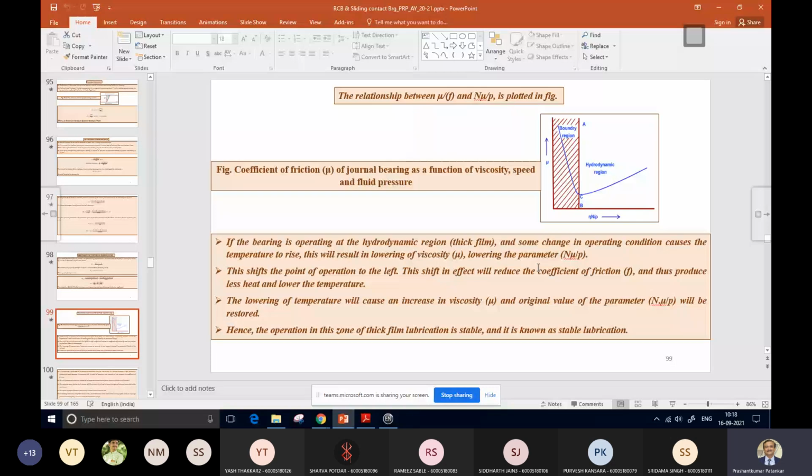After some time, when the temperature of the oil increases, that higher temperature oil is recirculated to the oil sump, wherein a provision is made to cool it, and it is again recirculated back to the bearing. That kind of thing is done, but it is costlier. So as far as possible, by making use of fins, try to increase the surface area. That is the simplest way to take care of the rise in temperature of your lube oil.